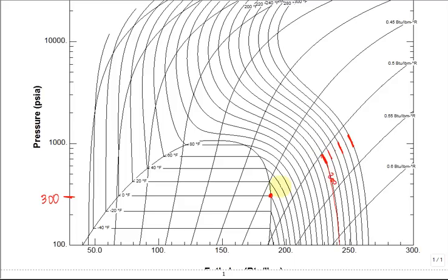Let's stop it when it's 200 and it looks like it's isentropic. What's that, right there? Did I do that okay? What pressure is that? It's quite high. It's up in this ballpark. This is 2,000. You have to read this diagram, but it looks like it's what? 1,400 psi.